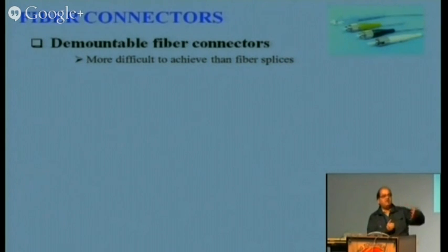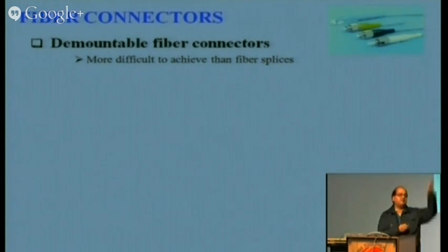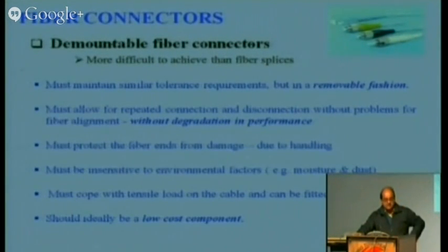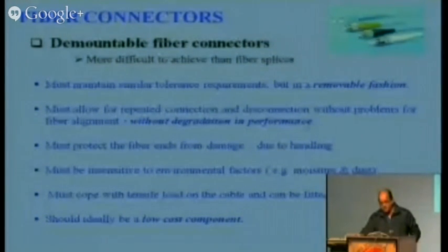The connector can be mounted maybe 500 times or 1000 times. So all these are the factors. It must maintain similar tolerance requirements, but in a removable fashion. It must allow repeated connection and disconnection without problems of fiber alignment, without degradation of performance.